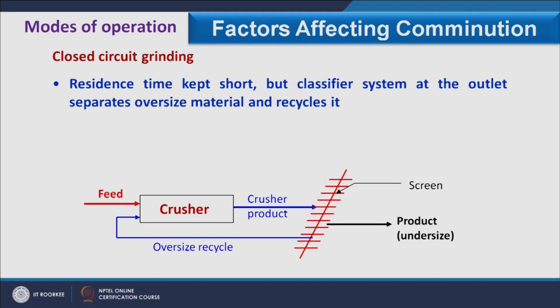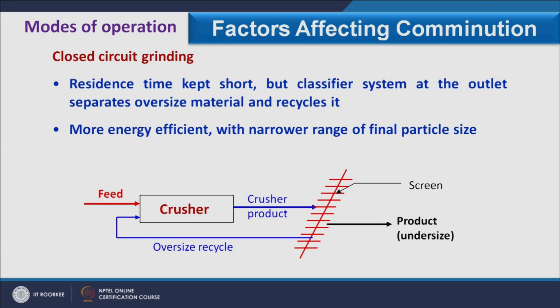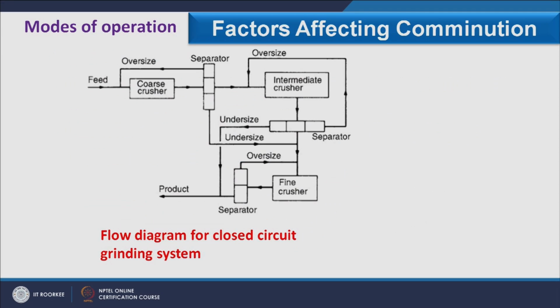So, in closed circuit, residence time is kept short, but a classifier system at the outlet separates oversized mineral and recycles it. More energy efficient with narrow size range of final particle size. Additional cost of classifier system is included in this.